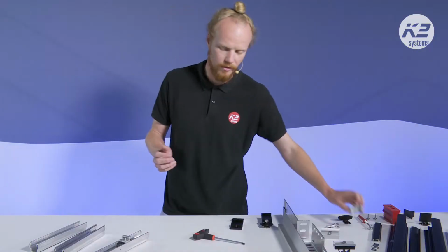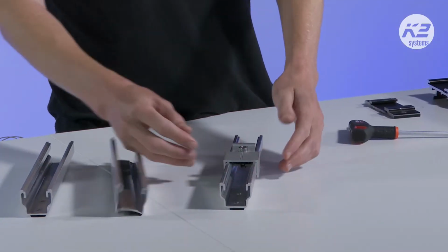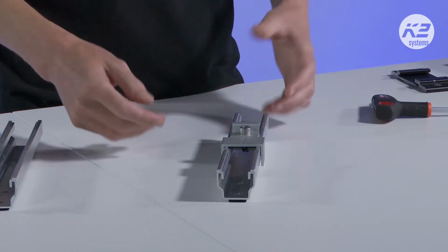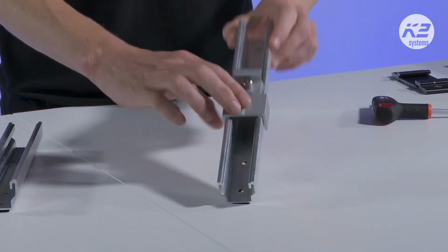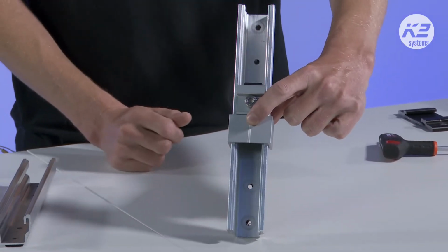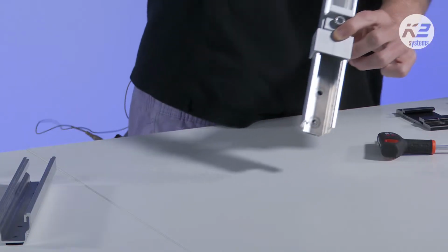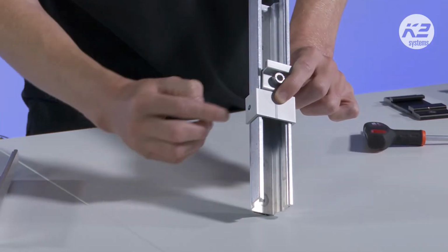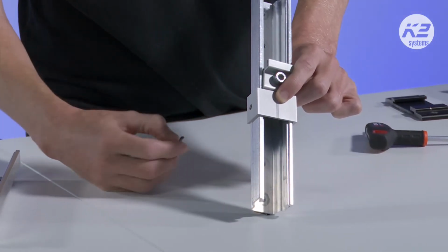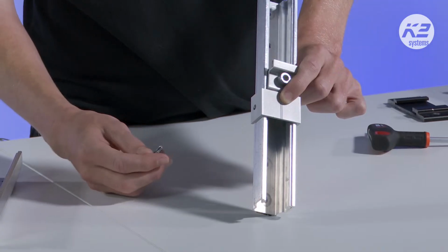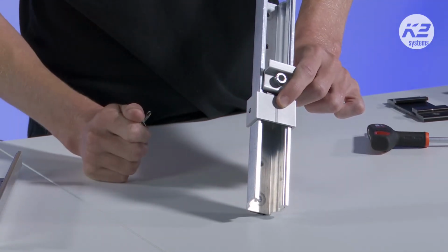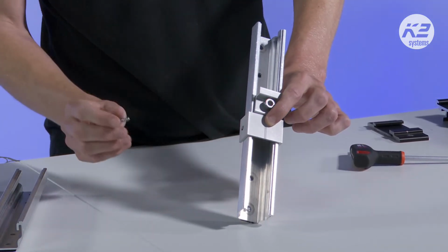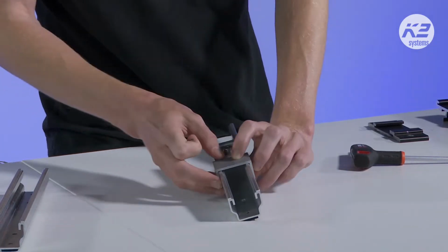Another slight addition is an anti-slip plate. This is one of the few fixings that we have into our own rail. Usually we have a bolt and nut combination, but with this product we will sit it here and actually screw through the side with a screw. So we're going to make a penetration into the rail, and this is effectively an extra level of safety, just in case something was to happen with the bolt in here and it was to loosen. And of course the clamp that's sitting on top holding the panel, we can put these in as well. Right, so these are the two main differences.